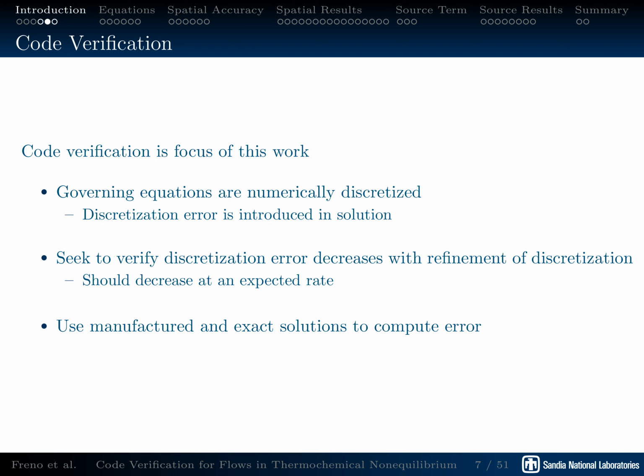When the governing equations are numerically discretized, a discretization error is introduced into the solution. As the discretization is refined, the discretization error decreases. More rigorously, the discretization error should decrease at a certain rate. To compute the error, we use manufactured and exact solutions.